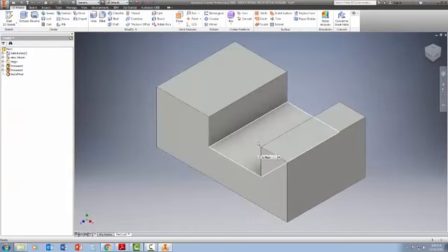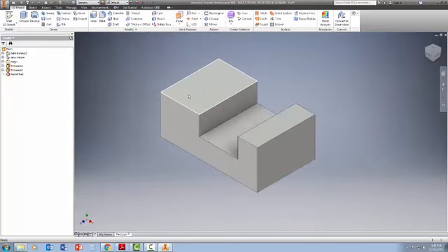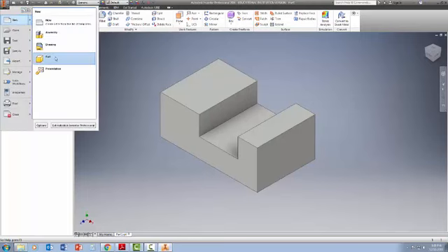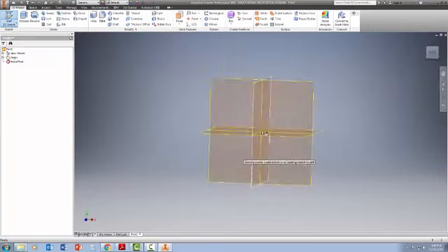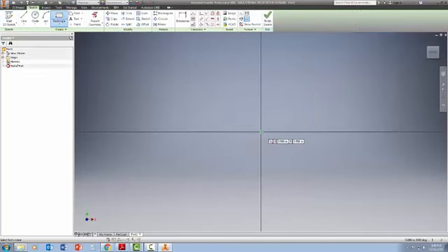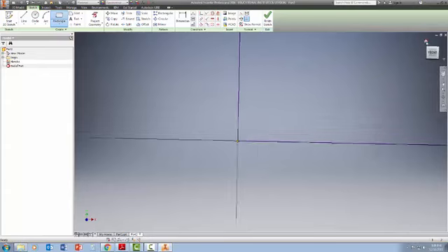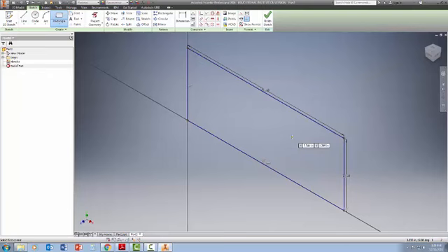Okay, now we're going to work on Part 2. File, New Part. We're going to start the same way, so I'm just going to speed up through this. Start Sketch, Front View, click on the front plane. Here, the center where it turns green. 5, and in this case, I don't have to hit Enter, I can just hit the Tab key, and it will tab down to the next measurement, 2, hit Enter, and if I click on Home, it'll give me a 5 by 2 box.